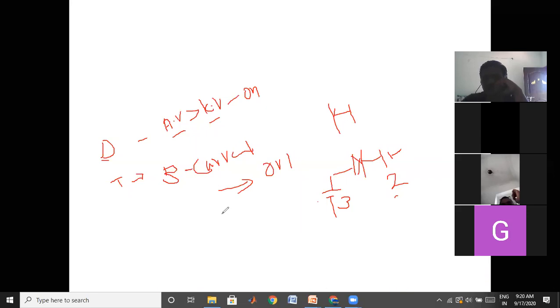Once the transistor is on, the collector and emitter will be short circuited. That means the current will flow from the collector to the emitter. In this way, current will flow when you apply the base signal. If you don't apply the base signal, there won't be a connection between these two, and the output will come from VCC.